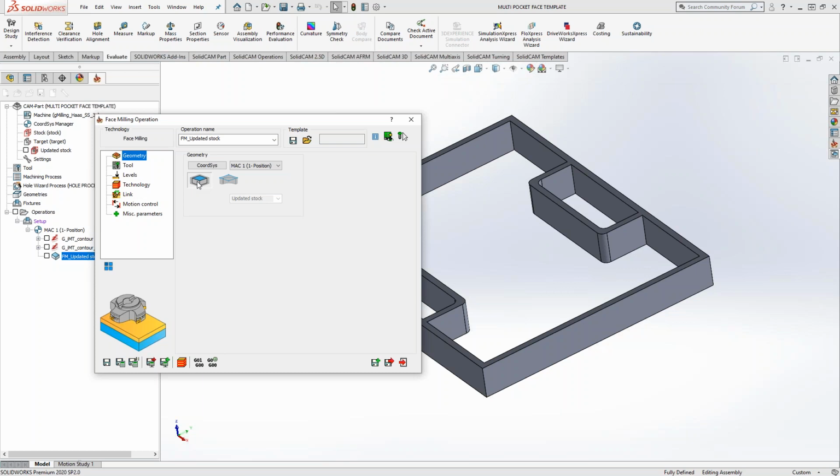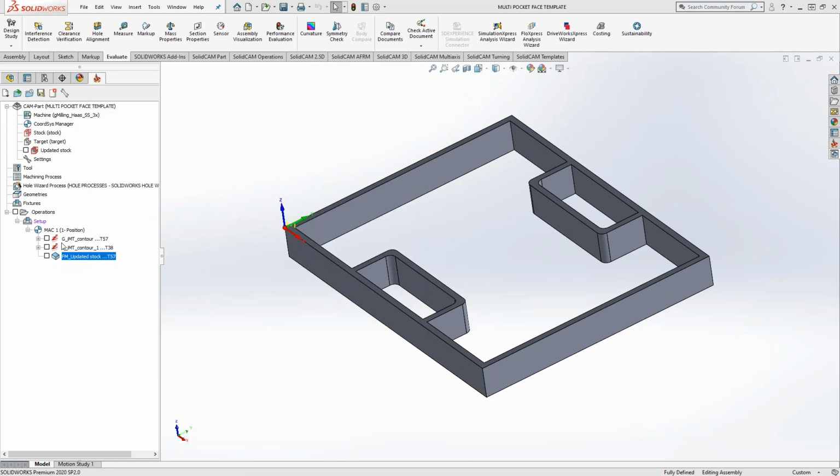This is really good, because any of these recognition toolpaths can now be used in a template to add even more of a time saving in terms of programming. I can just load this template and just synchronize and calculate. I don't even have to choose geometry anymore, because this is automatically going to look at the geometry for me. So I included it on this one. I actually could have done one 3D iMachining and then get it to recognize the geometry for me.